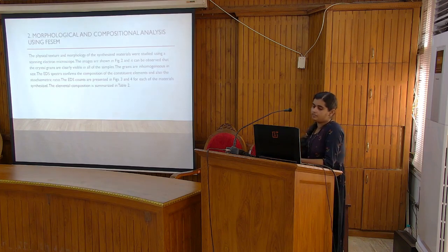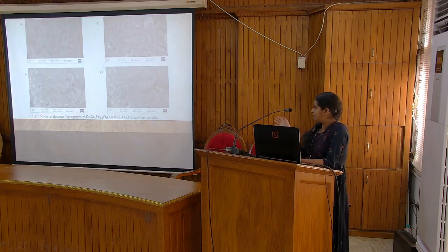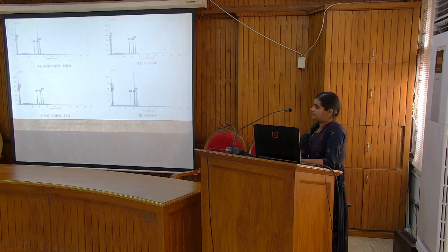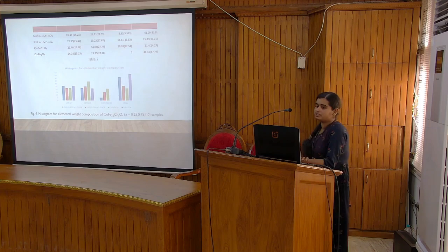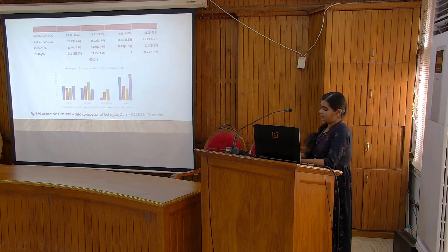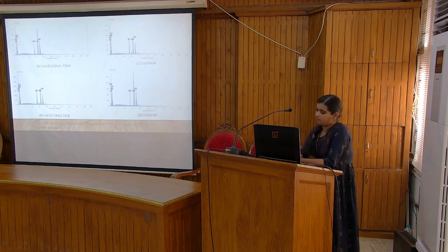From the figure, we could understand that the crystal grains are clearly visible in all of the samples, and if you look closely, we can see that the grains are inhomogeneous in size. And here is the EDX spectra of the samples. From this, we get the elemental weight compositions. In Table 2, I have given two values: the bracketed one is the theoretical, and the other value is what we obtained from the EDX spectra.